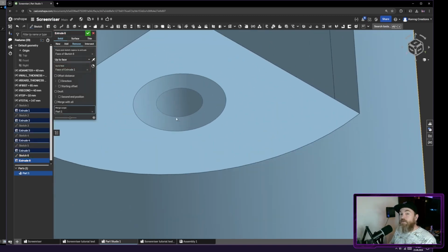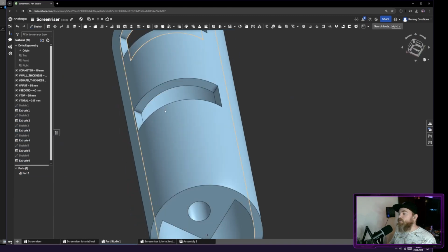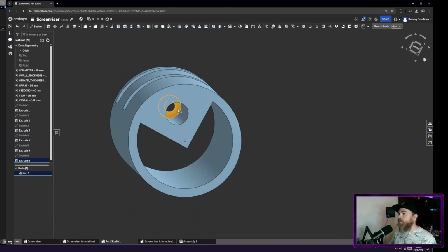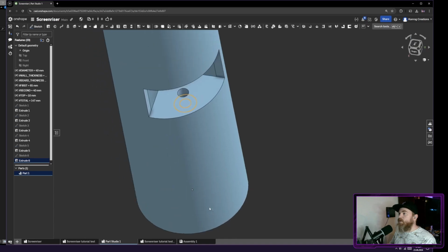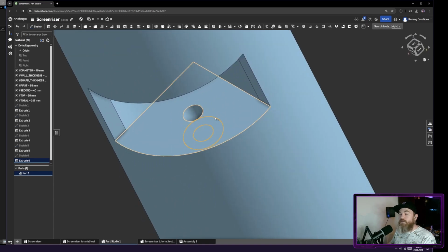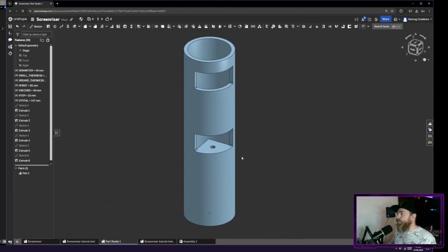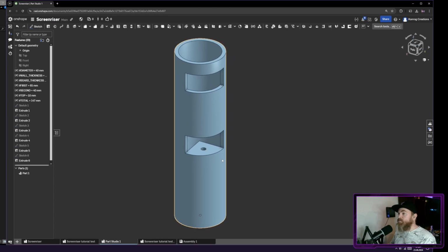Now it'll go all the way through. We don't want that. So let's offset that. And I'm going to offset that by 6 millimeters. And if I now hit OK, this hole will start at the bottom and go almost all the way through, but it will stay always 6 millimeters from this reference line or plate surface. And that is looking good, I must say.